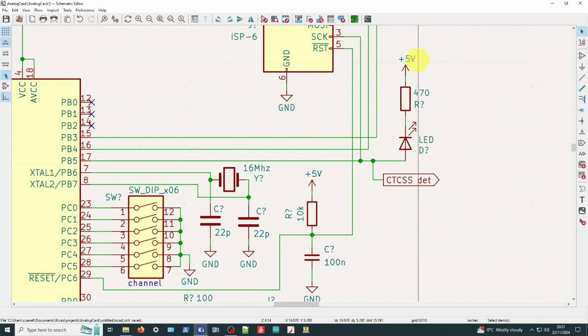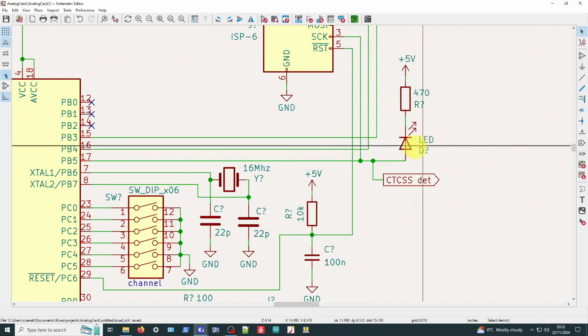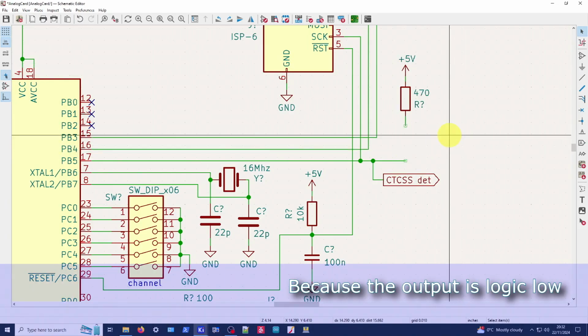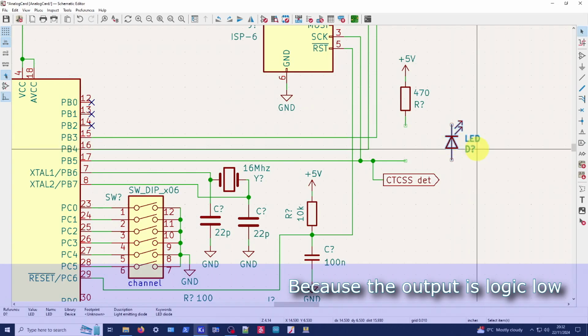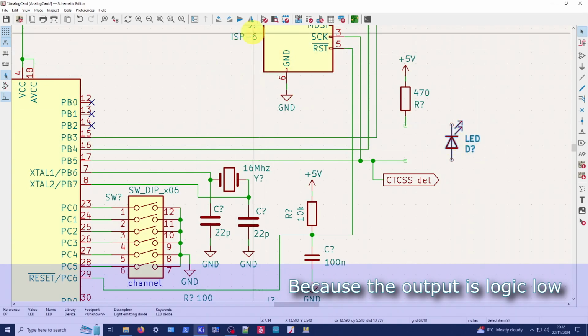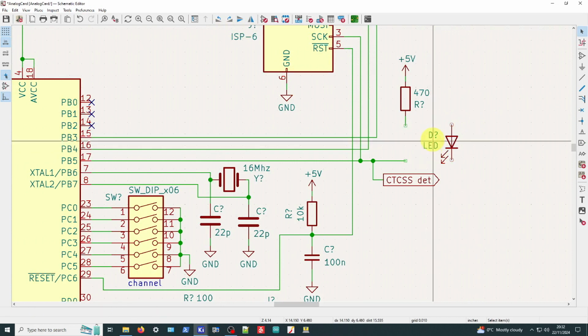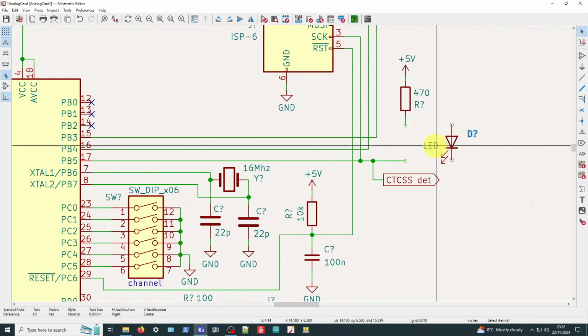And also we've got an LED, which I've just realised is round the wrong way. Ha! Gotcha. Let's fix that right now. Put that there, and we need to rotate it. Press R. There you go. And I'm going to shift the legend over to the other side.